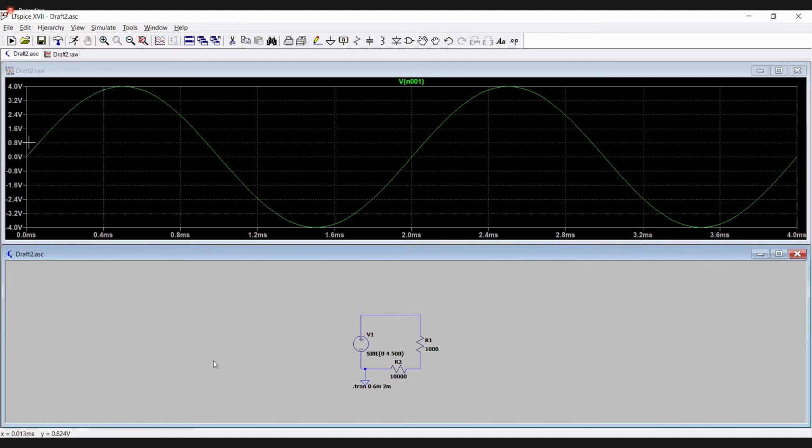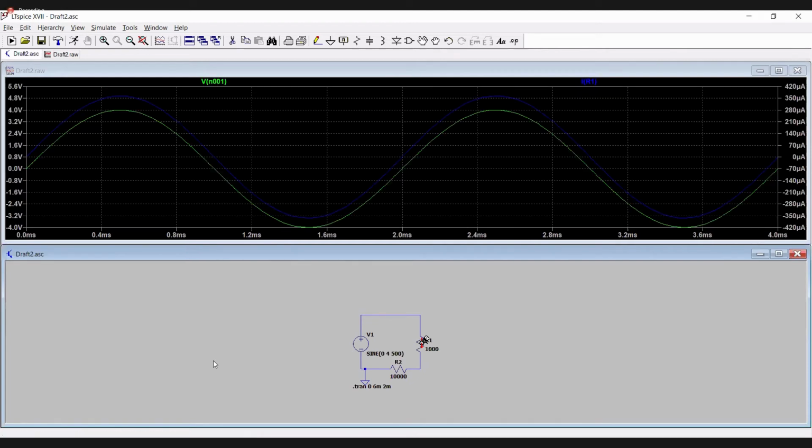So what I explained in terms of phase angles is the relationship of phase angles between your voltage and your current. What did I say a while ago? I said that they were in phase, no? That the voltage and the current across any resistor are said to be in phase, or they would peak at the same time. So when I measure the current here, this is just a series connection, so the current is equal in all of your components. For example, I measure the total current here.